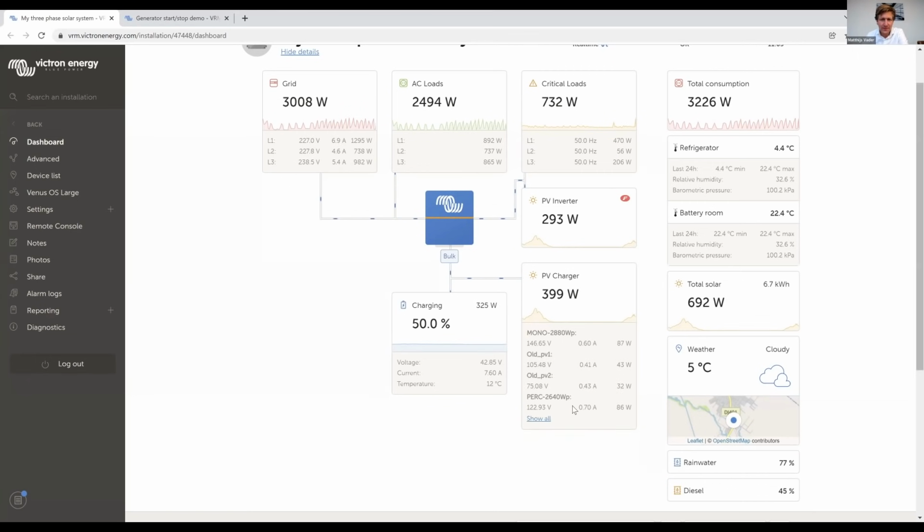Then next, the frequency of the AC output was added. Already available now. And this is useful mainly for AC coupled systems. So this system is now connected to the grid, but an AC coupled solar system off grid will control the power coming from the PV inverter by increasing the frequency. So people familiar with such systems and troubleshooting them or keeping an eye on them are often keen to see the output frequency. And we've added that here in this extra details box.